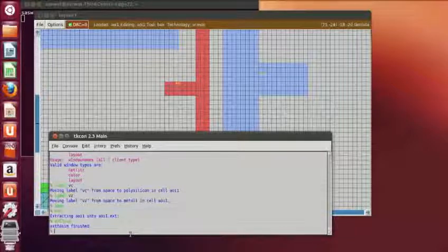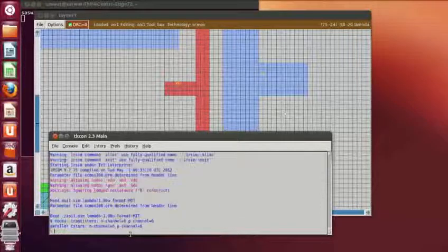Now after extracting the sim file, next we have to simulate this in IRSIM. So type irsim AOI1.sim, then w, that is watch, VA, VB, VC. There are three inputs, VA, VB, VC, and the output is VZ.